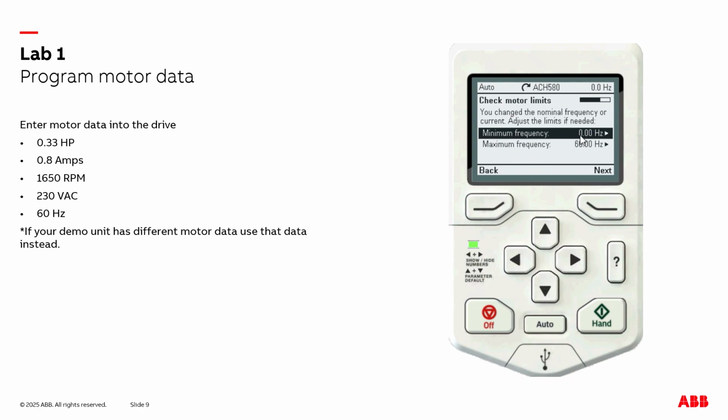This is an area, if you wanted to set up a minimum frequency for the entire drive, which would apply to hand and auto mode, you could also do that here. But we're just leaving that alone at default, 0 to 60. And then it's going to ask us, are you about to exit the assistant? Do you want to save the settings? Yes, we do. So now we've programmed in the motor data into the drive.